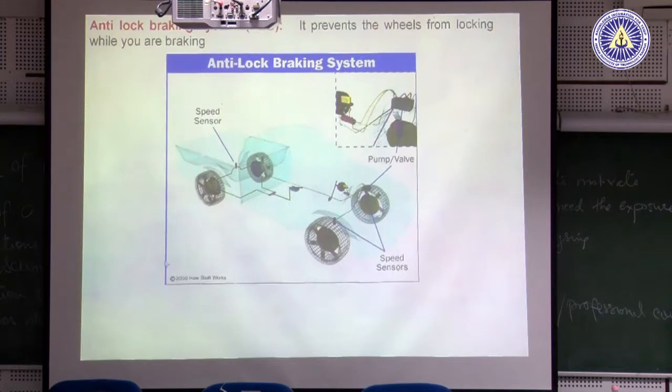For the mechanical engineers, for example, a nice example is an anti-lock braking system. Traditional braking of a car is a mechanical hydraulic system or whatever it is, right? But in this case, if you add electronics to it, then you mount sensors on each one of those wheels. You can monitor the rate at which the wheels are rotating, and based on any difference in speed, you can apply more pressure to one wheel or the other. So you can have an intelligent braking system, an anti-lock braking system, basically by adding an electrical subsystem to your braking part here, right?